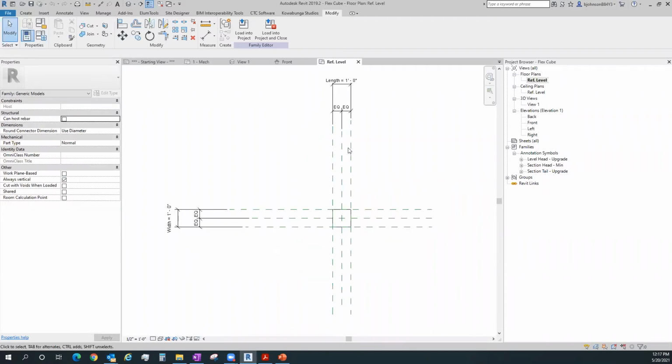And then all of my reference planes are the things that are dimensioned. So my length, my width, and my height are just those feature parameters. And I can turn this into whatever I want. If I want to have 10 different objects of 10 different sizes, then I can merely just go in and change those 3 dimensions, what their values are for length, width, and height. If it's going to be sitting on the floor, I don't change my base offset or anything. I just let it sit there.